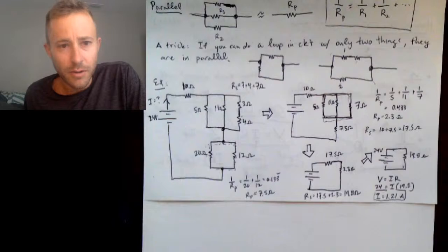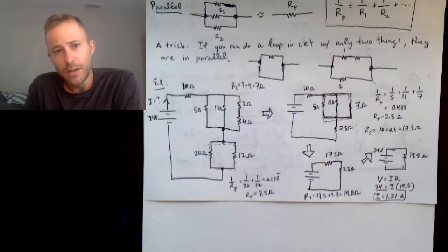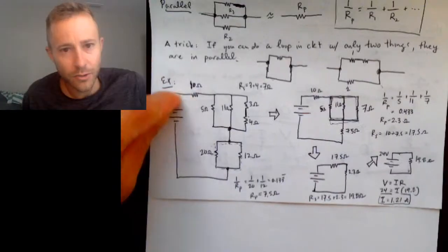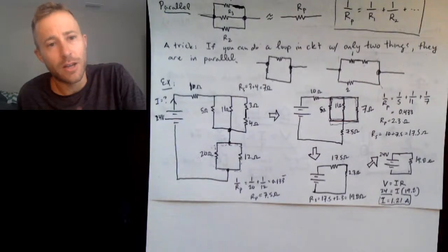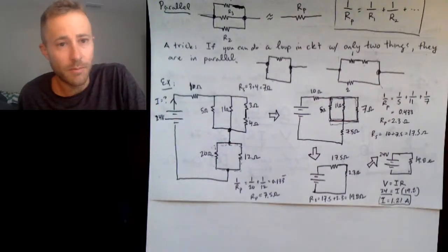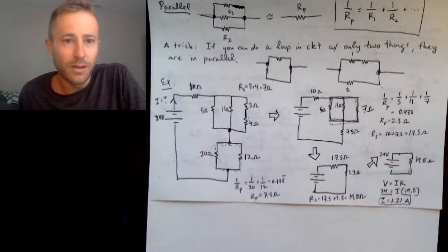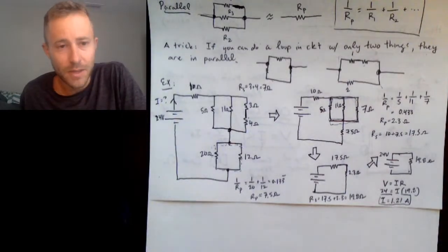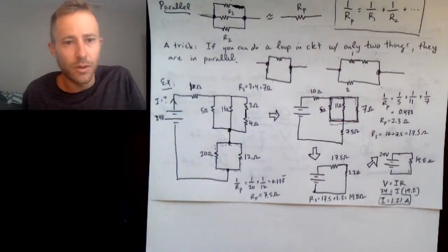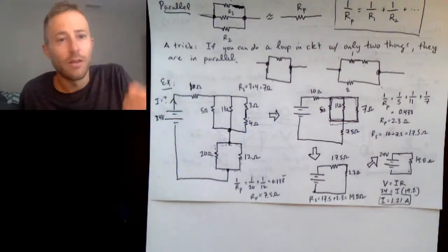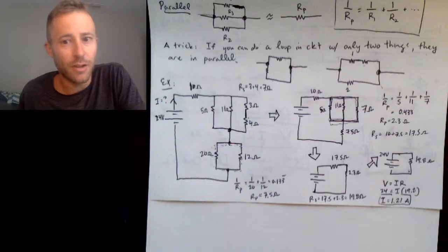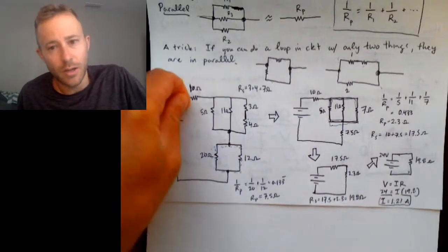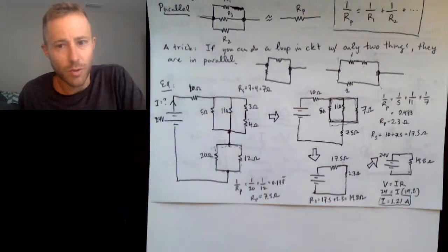The other thing that this has implications for is it would tell you how thick these wires need to be, all right? The more current a wire is carrying, the thicker the wire needs to be in order to not get too hot, all right? So, if you try to drive a lot of current through a really thin wire, that wire is going to get incredibly hot and it's a fire danger. Okay, so you want to know how thick do you need to make the wire. So those are some reasons why you might want to know the current flow. All right, so that's